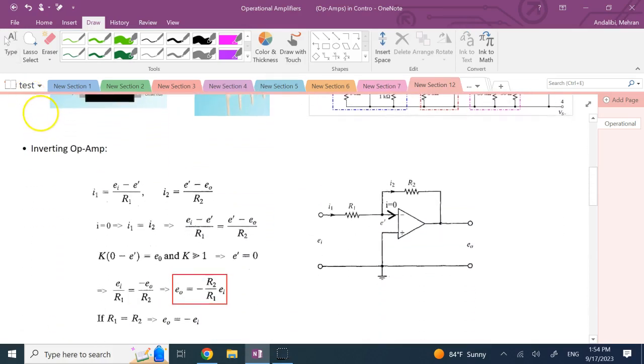For instance, a simple circuit you might look at is this one here, where the two signals that are going in, one of them you grounded, so this signal is basically 0 voltage, and the other signal going in, on the way you have this resistor and it goes to the negative port. Then you have this branch coming out with another resistance, R2, that goes to the output. And now you want to know what is the relation between EO and EI here.